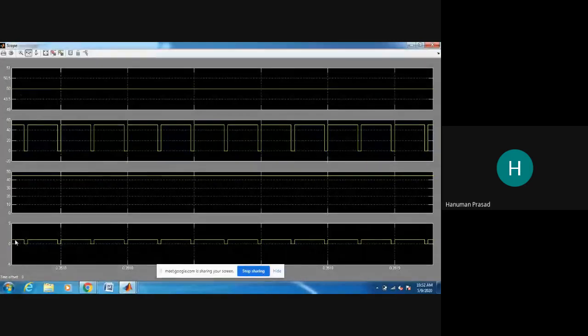When the pulse is on, you are getting 45. And again, when the pulse is off, which is only 10% of the duration, at that time you are getting the output voltage as 0. And again you are getting the output voltage as a pulse, and this is the filter output voltage. The filter output voltage is near about 45 or 47 volts at 90% duty cycle.